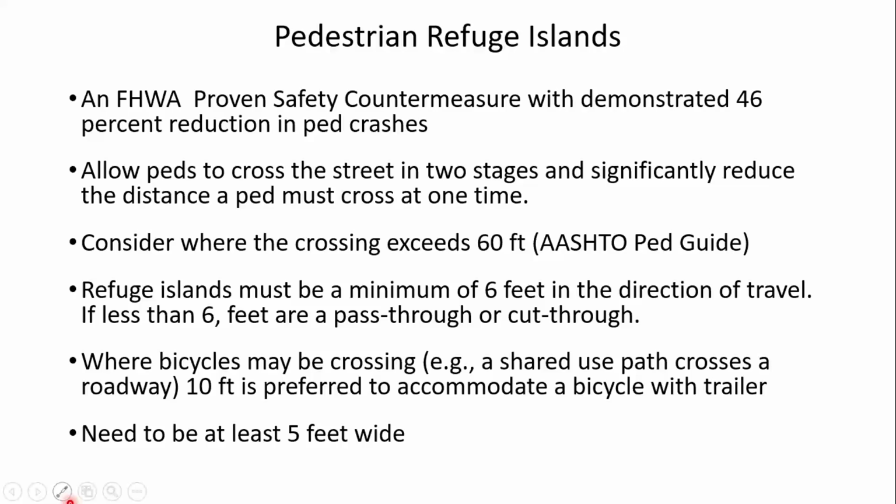The refuge islands must be a minimum of 6 feet in the direction of travel. That's per PROWAG. And if they're less than 6 feet, they're not considered a refuge area. They're considered a pass-through or a cut-through.